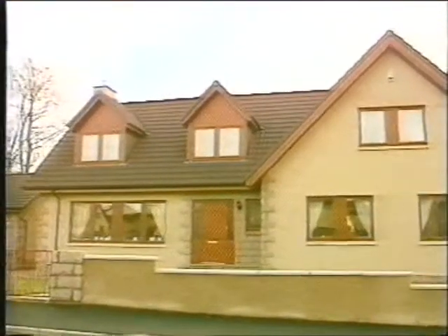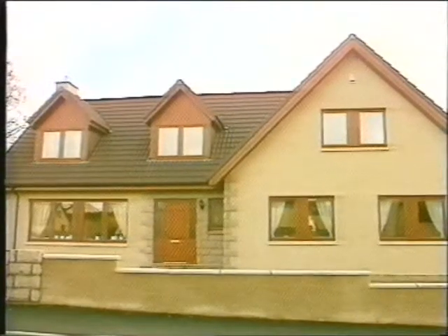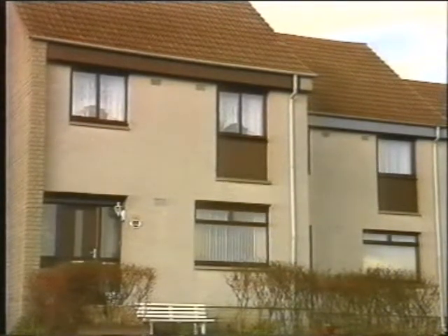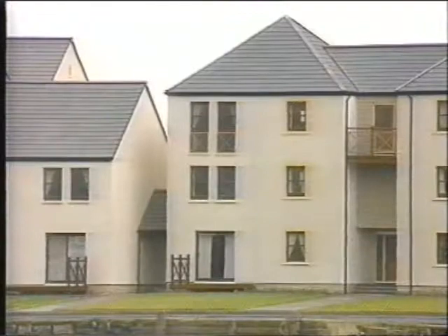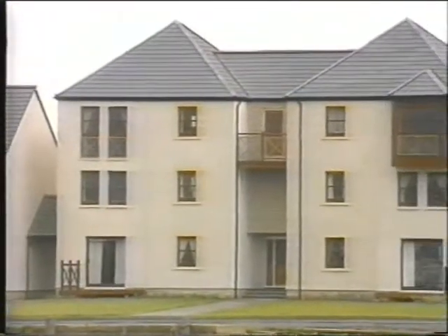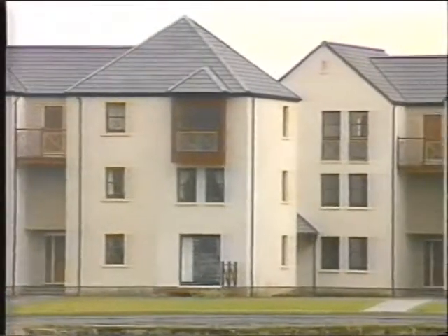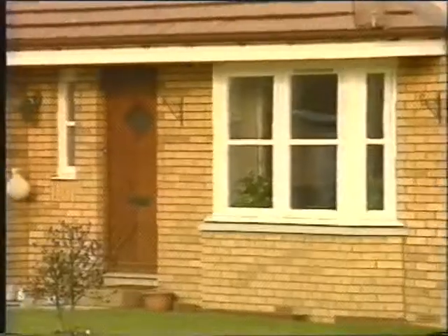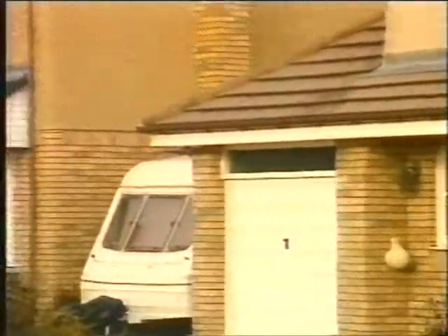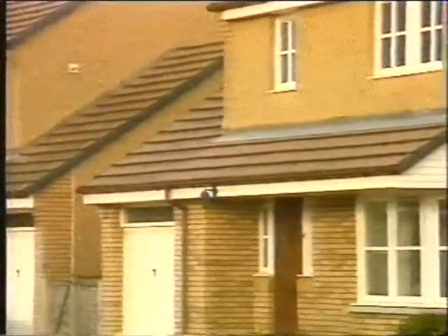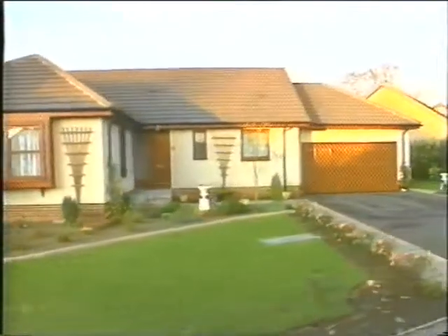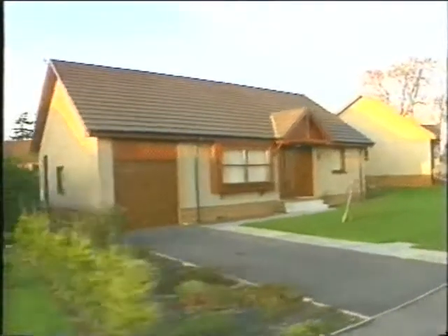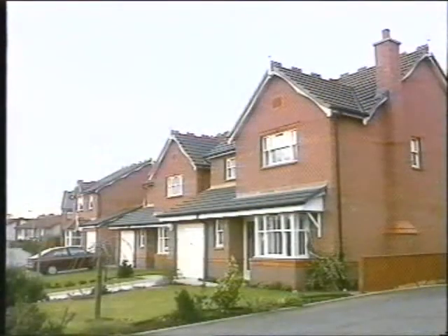For the large house, with its greater demands, the S plan might be the preferred option. The semi-detached, with its less extensive requirements, might be fitted with the Y plan. And the flat, where there's no room for a header tank, may need a sealed system, and because there might be fewer taps, it might be suitable for a combination boiler. But there are no hard and fast rules. The bigger houses might benefit in some circumstances from having sealed systems or combination boilers. It depends on space, the number of taps that may be used, the family's requirements and so on. It's important to assess each location on its individual merits.